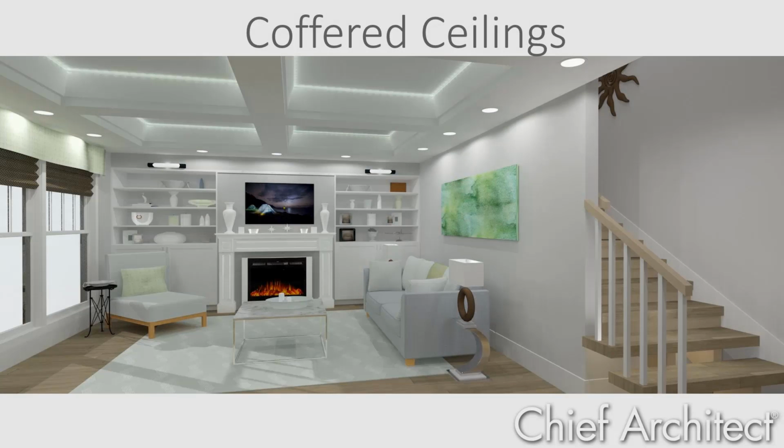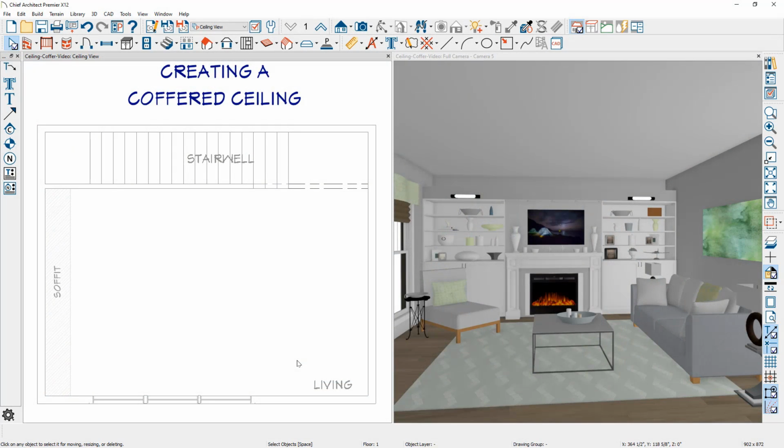In this video, we'll take a look at how to create a coffered ceiling. Creating a coffered ceiling can be accomplished by using the tray ceiling tool. Let's take a look at the steps to create a couple of different coffered ceiling styles. In this sample living room that I have open, I currently have a 9-foot ceiling with no particular ceiling treatment.